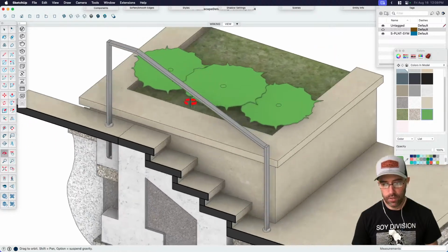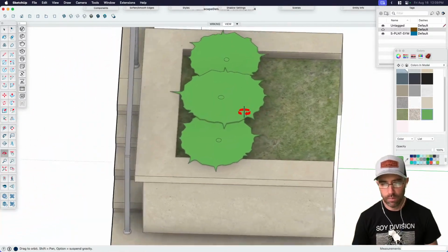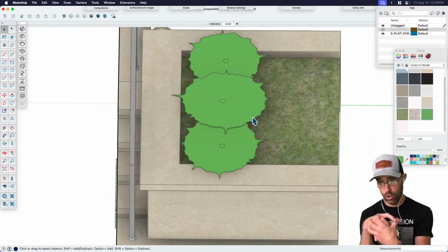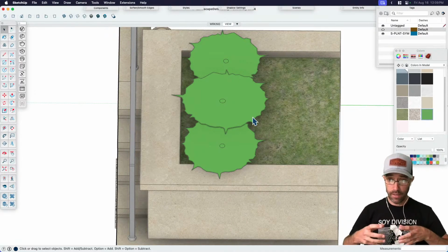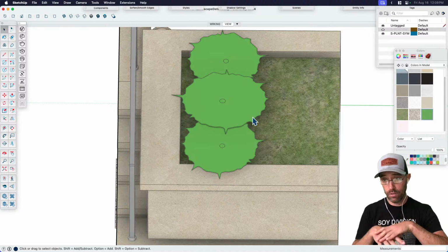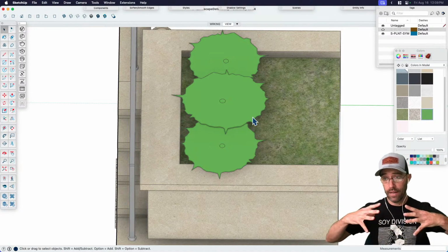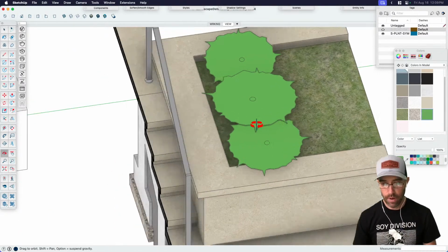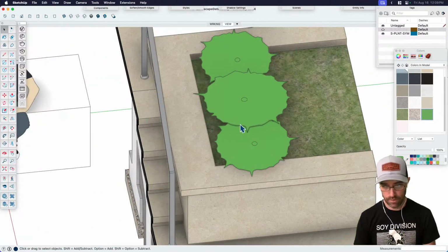Kind of looks cool. It looks like saw blades, or it looks like cogs, where it's like a machine is turning. Because I put them inside of a face me component, the face me component is turning. If you didn't want to do that, you'd make a new component container. So you'd have the face me, and the symbol, the 2D plan view, would stay, and then the face me would rotate, but the container on the outside wouldn't. That would be static. That would stay still. So if the little rotating symbol bugs you for some reason, you just have to set that up differently.